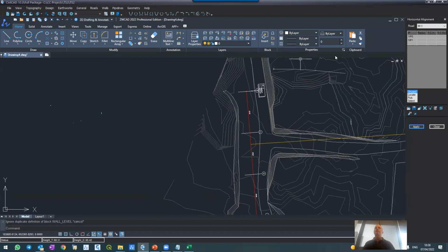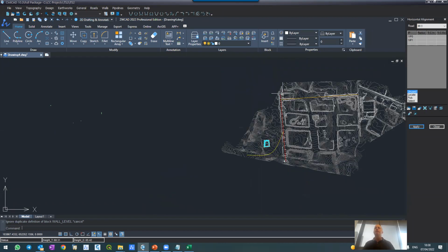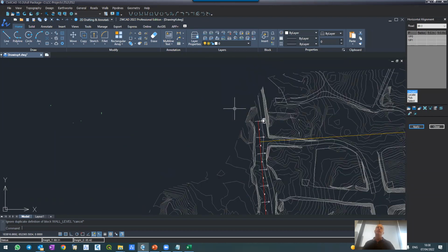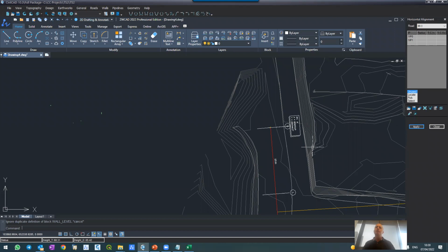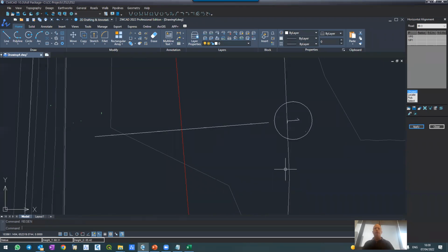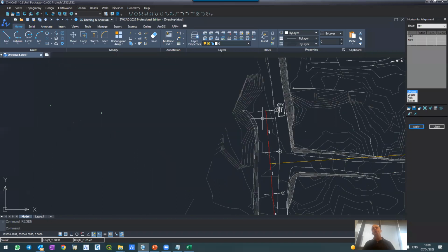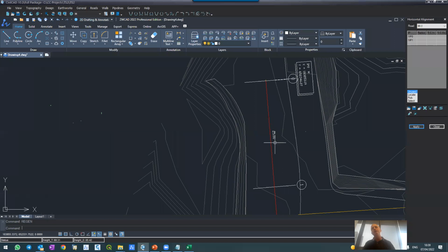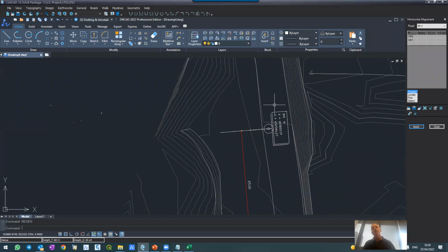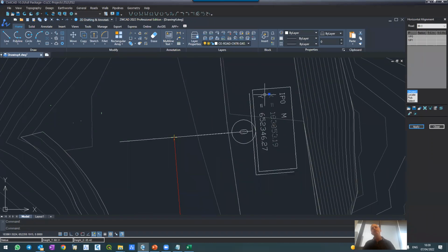So I created the surface of the existing before and another surface here. All of them are BIM modules. Here now I start creating a BIM of the road. So I have numbered the road, the cross sections. In this case, the system used a default of 25 meters between cross sections. Give it an IP here. I see the system uses text.